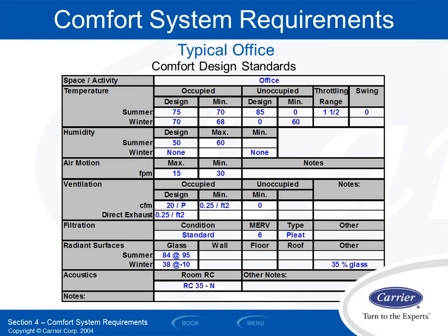setback, if you will. Traditionally, the bigger the setback, the better the energy savings has been, right? Most equipment that you had in a lot of existing systems was one-stage equipment, or even to lesser degrees, sometimes you'd have two-stage equipment. And when I turned that equipment on the next morning, I pretty much turned it on, let it go balls out, try to satisfy the set point, everybody's happy. And the bigger the setback I had at nighttime when no one was there, the more energy savings I would have. Because remember I said that the heat transfer rate through the wall is a function of the delta T through the wall. The bigger the temperature difference, the faster the heat transfers.